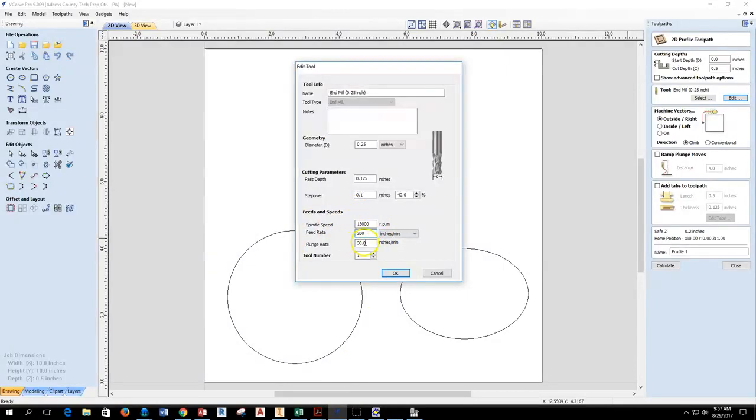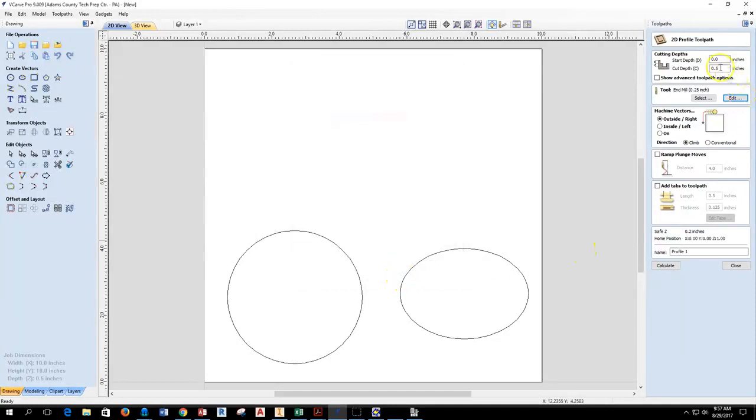Keeping my plunge rate set at 30, I'm going to now just keep moving forward and hit OK. Coming down further, I want this to be my finished piece, so I want to set this up. I'm going to be running conventionally around the outside of the part in a conventional run. And as I keep coming down through, I'm going to set this up to...